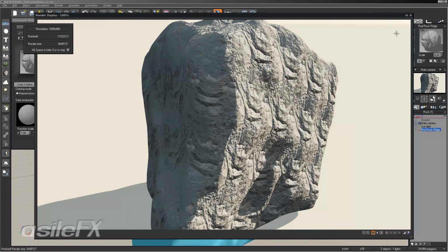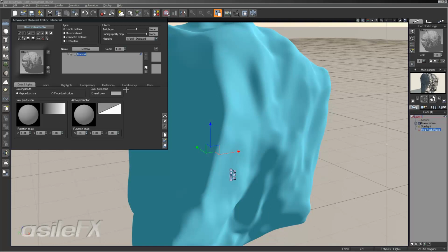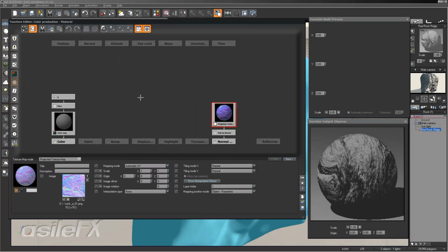Normally, the UV mapping mode is the only way to really prevent the scaling. In previous versions of Vue, there used to be an unscaled UV coordinate, and that's been removed. And now we have to rely on the UV mapping mode. So if you want to make modifications to the overall scale of the texture, you will need to kind of compensate with the texture map.